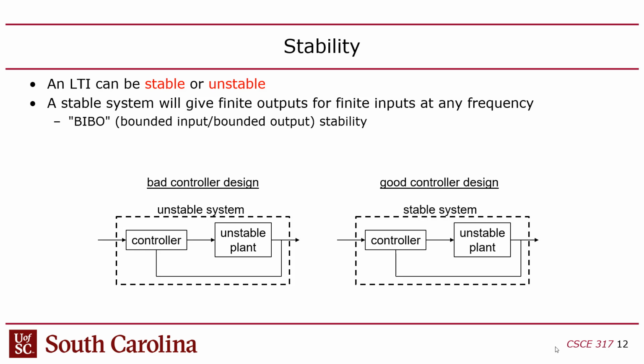Now the problem is that the plant itself is usually unstable. For example, even in a car, assuming you realize it as a linear system. If you think of your car, if you just apply a constant acceleration and you assume there are no non-linearities, then it'll just accelerate infinitely, right? It'll never stop. That's unstable. That's an unstable transfer function.